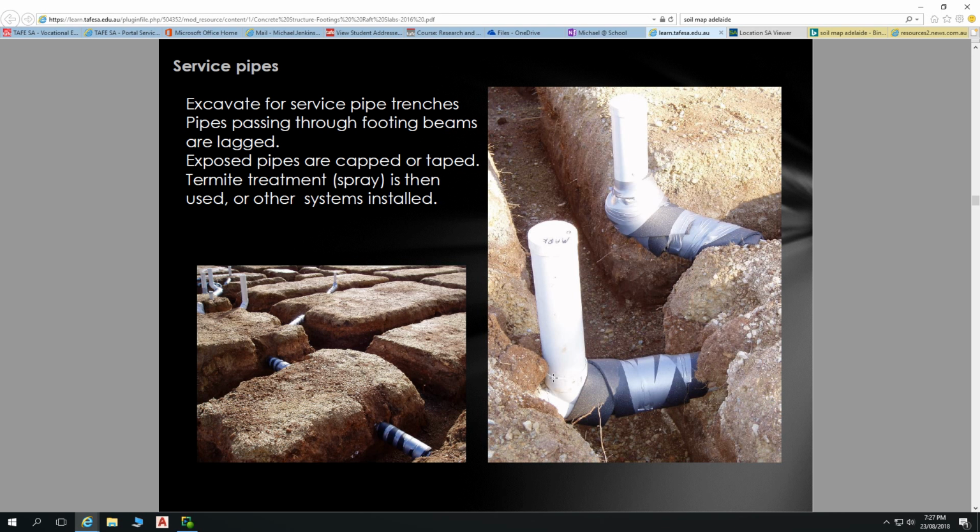Because certainly what you don't want happening is snapping of pipes underneath your slab. That's probably worst case scenario, which you can get. So we've got some beams happening here. This slab's going to be moving. That pipe is in that soil, going between those 2 things. You may end up with having forces transferred and cracking pipes underneath your slab if there's a lot of reactivity and you don't have any lagging. But also you get snapping of pipes right at the edge of your concrete as well, without that spongy lagging.